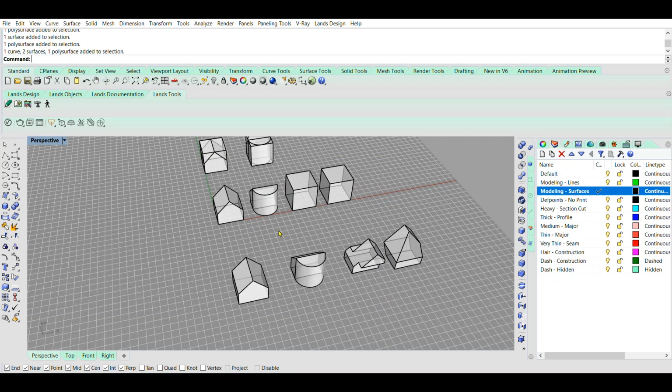I'll show you both, but the other one is we can actually use an unroll surface command to have Rhino unroll and project the surfaces to a C-plane. If using this method, test the different outcomes when you explode, label, and keep properties. The unroll command will likely send the unrolled surfaces to the 0,0,0 C-plane world origin.